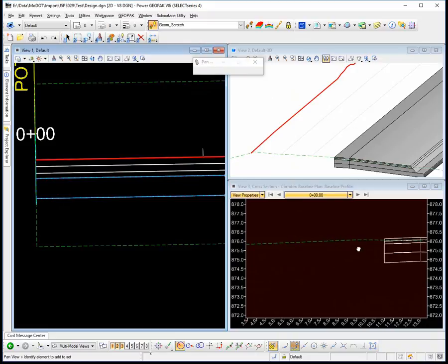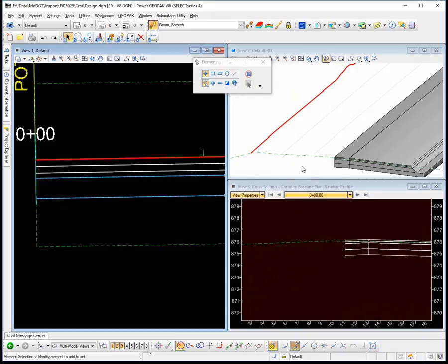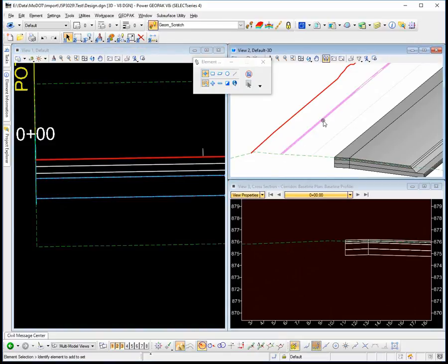It'll be projected through that plane, and then match the existing based on those parameters. And so I really don't even need those point controls now because I'm parallel to my baseline. If I weren't parallel to my baseline, perhaps you might need to use one of those point controls and alignment for simply a horizontal control and not a vertical control. The key here is to not use the vertical profile of the existing ground if you don't have to.